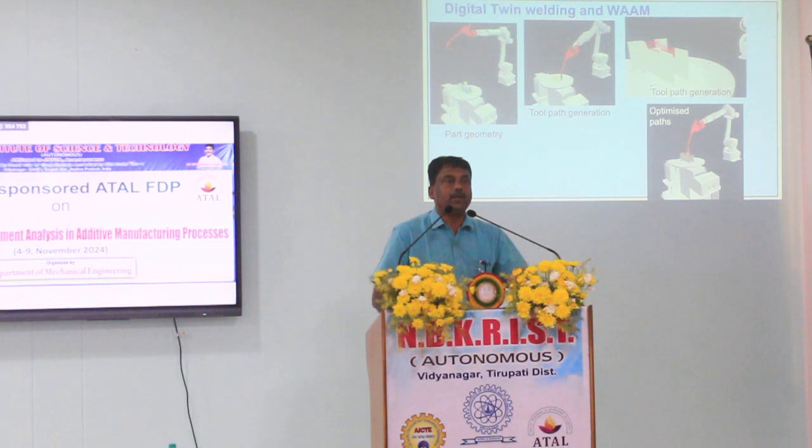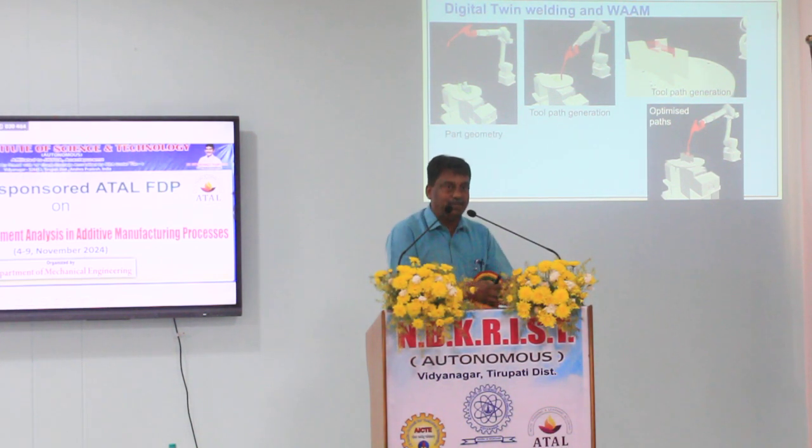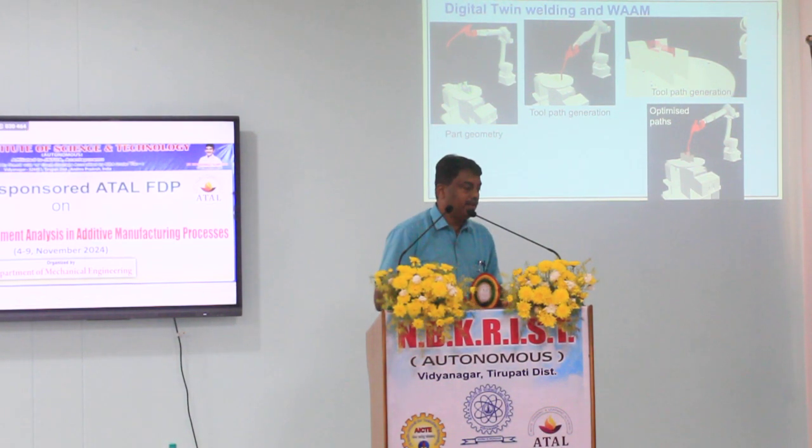Subsequently, when we build layer by layer, we can program each vector's welding arc energy continuously, so that we can introduce the required temperature gradients which can dictate the microstructure, or we can mitigate residual stress as and when needed. Once we have such systems, we can visualize the complex loop part we generate, and see how the entire part is built in the digital twin before even printing, and then subsequently take it up for the final printing.